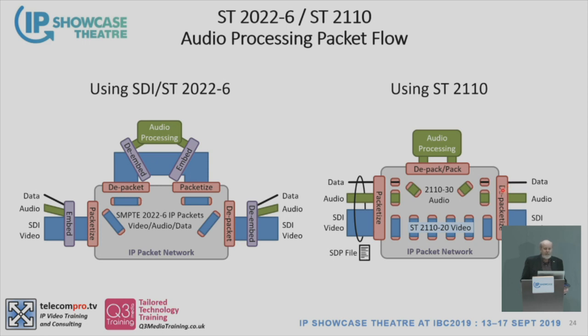Now, there is a cost to this. First of all, I need a way to associate the different streams together. That can either be done in session description protocol using the SDP file shown here, or it can be done using NMOS, which of course we'll talk about later. So that's going to name the resources, going to tell us which particular signals are associated with each other from a master control system standpoint.